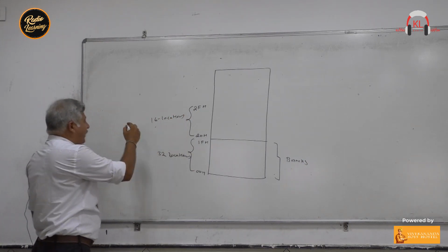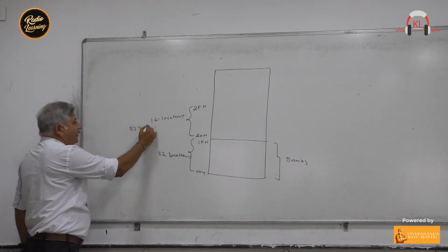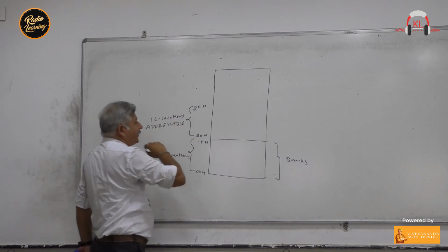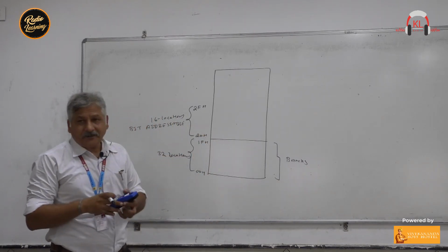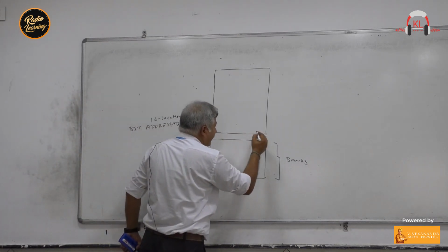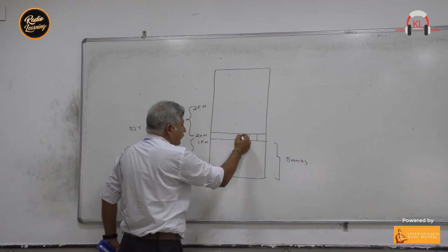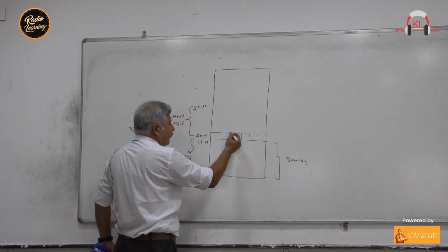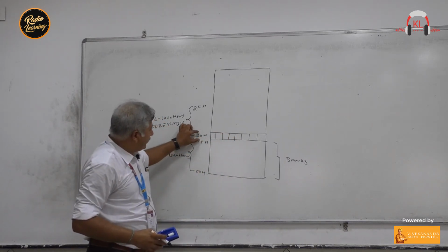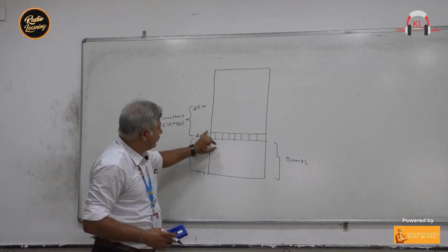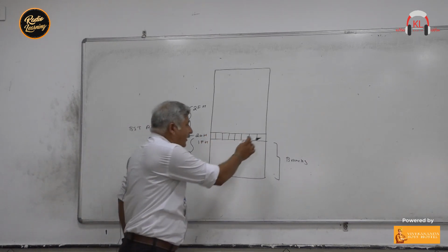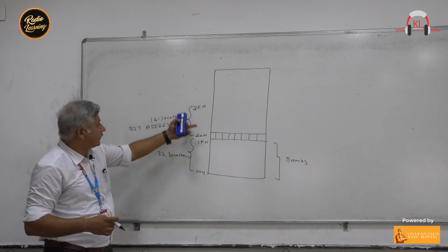These are 16 locations. And these 16 locations are bit addresses. Bit address. The meaning of bit address means you can access individual bits of these locations. For example, location number 20H. As I told you already, 8 bit sequence stored at this location. 1, 2, 3, 4, 5, 6, 7, 8. So here at 20H location, you are having 8 places where you can store the bits, and you can access the individual bit also of these 16 locations,